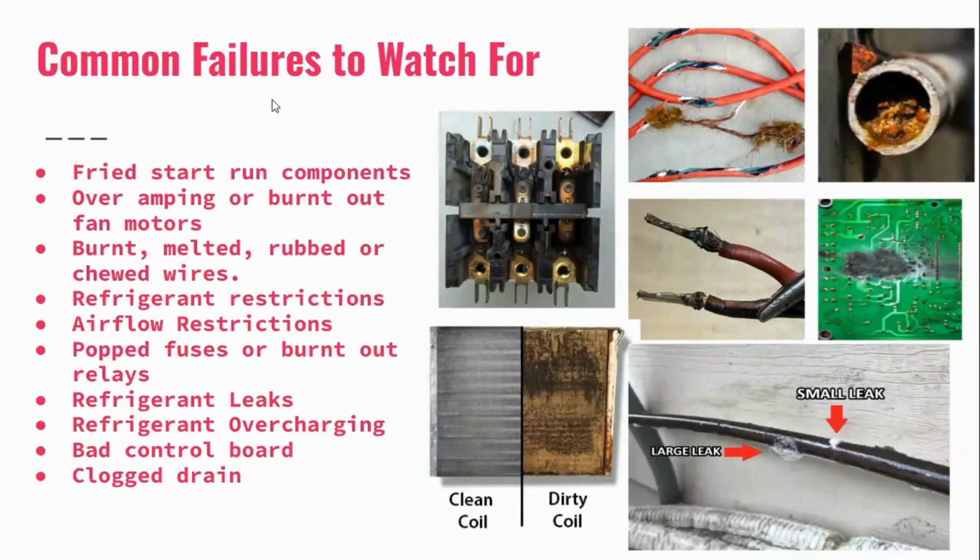So then we have common failures to watch for. I grabbed the worst of the worst, obviously. You will not always see them this bad, but this is what I want you to look for. I'm always pounding on you guys about non-invasive system check, and one really good way to do that is to look for visual signs. We talked about listening for the reversing valve. That's another great one. Use your senses. Your senses are the best tools you could possibly use on any job, especially a diagnosis or troubleshooting job.